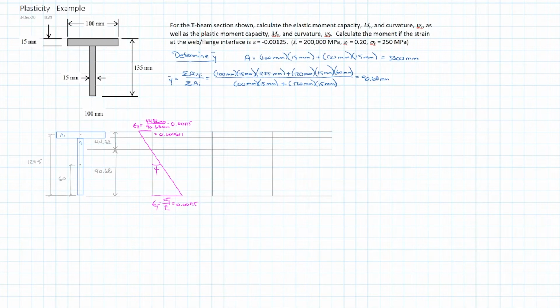So from there, we want to look at the stress diagram. Because we're still within the elastic limit, the stress diagram will also be linear and vary from top to bottom, passing through the neutral axis. And the relationship, of course, because we're elastic, between the stress diagram and the strain diagram is that stress is equal to E times strain, or Hooke's law.